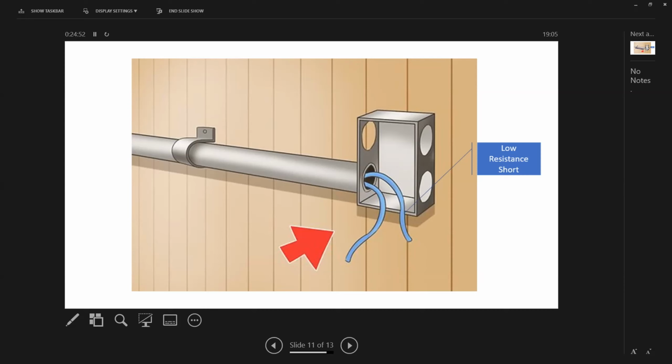There was the source of our magnetic field. Well, that current flow was the culprit. So how do we get rid of it? Well, the simple way to get rid of it was to go inside the box and reposition the wire and put the cover back on again.